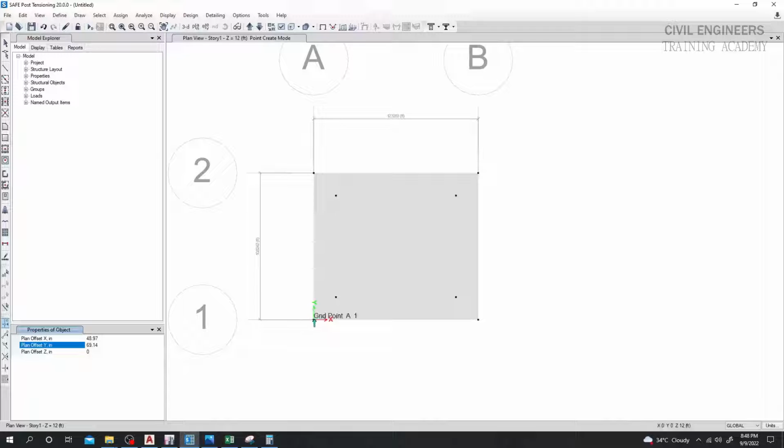When it's done, now I'll take a point here, and from that side just only the value of x will be minus. Then click here, and from here view, refresh Windows, just see here one point, here another point. Now I can place our pile cap.